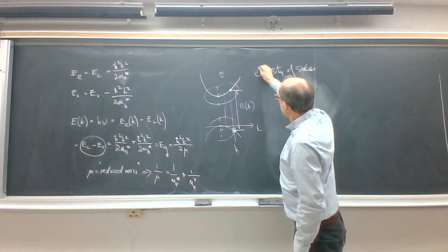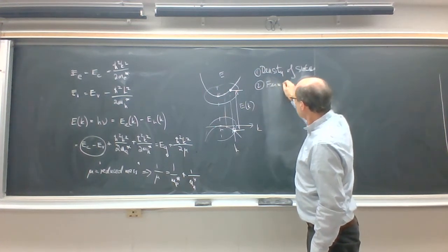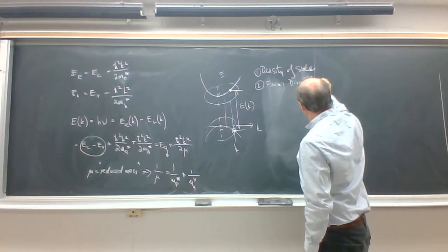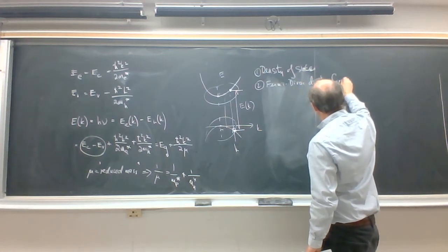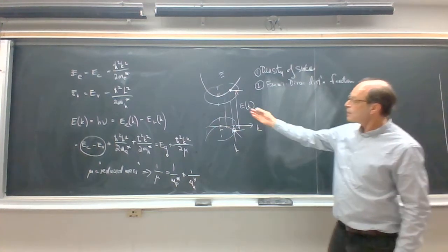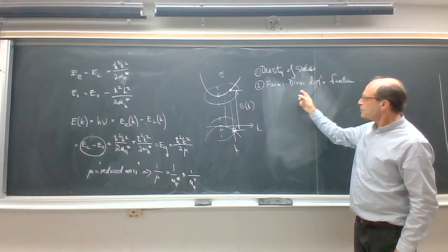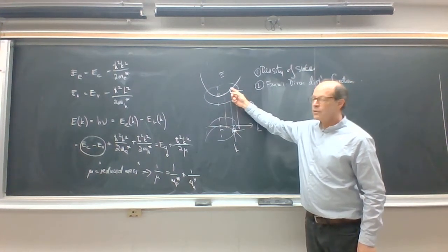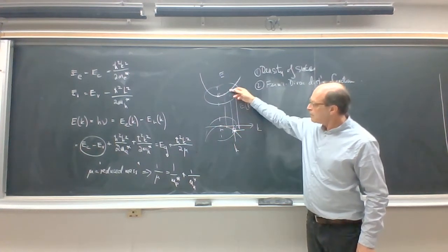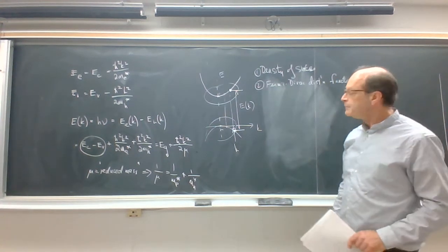And then the second thing we have to look at is the Fermi-Dirac distribution function. So we need to know both the density of states in the bands, and secondly, the distribution function to tell us if the electrons occupy those states and if the holes are available in these states for the electrons to recombine with holes at varying values of K.